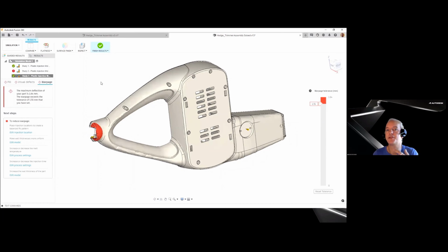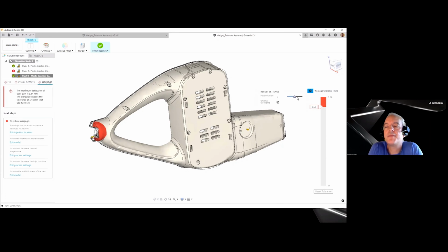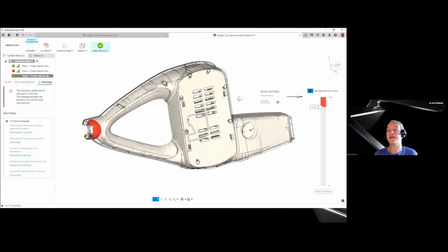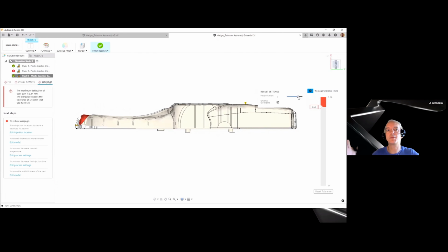There's actually 2 things I want to mention in this particular plot. First, if you go to the gear next to the plot properties, yep, there's a magnification slider, so we can magnify the amount of deformation we're applying. So you have a much better sense for how it is deforming. There's going to be a good amount of shrinkage, but also if you look at the red end, the corner on the left, there's a lot of out of plane deformation, and that could be a bit of a problem.